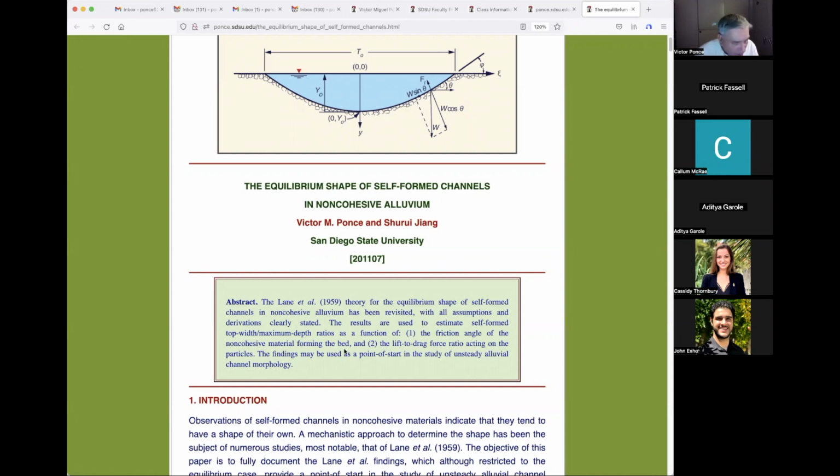And I know all of you have taken geotech engineering, hopefully, and know what I'm talking about, the friction angle. The friction angle is the angle of repose of granular material. And it varies between 20 and 45. 45 is for the huge rocks, 30 is for sand, and 20 is for silty sand. Actually, the friction angle could go below 20. It could go to 15 and 10. But the problem is that the lower it becomes, the more cohesion it has, and then you throw a monkey wrench in there. Exactly how is it that the cohesion is interacting with the friction angle to show the strength and so forth?